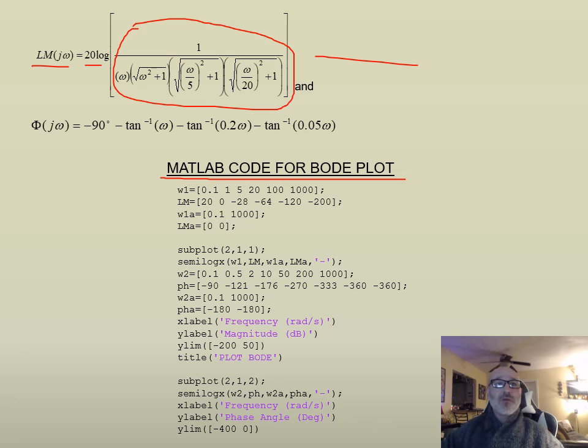So we can see we go through and define all of our values at the top within our MATLAB code, and we're calling out a subplot. Again, we want our phase and our magnitude on the same plot right here. This is kind of the old school way of doing this. There are new functions within MATLAB that we can utilize that are one or two lines. But I go through this just to show you how we can tweak our labels, tweak our values for our limits, title the plot, all this information we can do right within MATLAB.